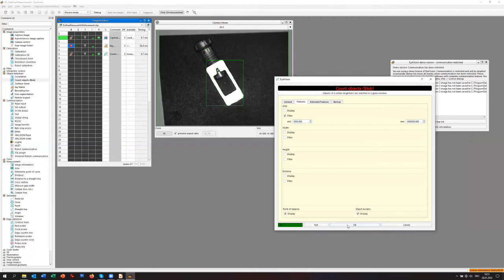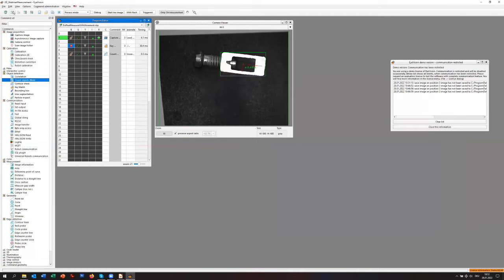And finally, we want to have some extended features. In our case, we want to use the eccentricity, which also generates a center point and an orientation point. This is what we need now for the moment. And if we move this, you see, we find the part always. This is a fast version where you don't have to think about a lot of stuff. So stop.